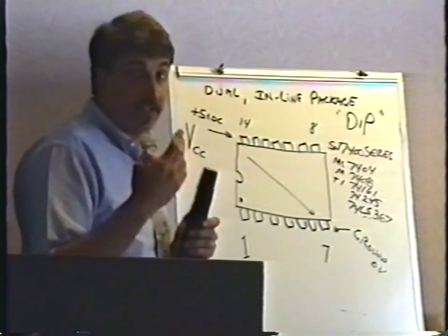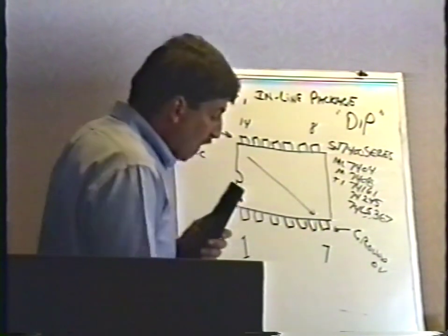And with the power turned on, I just go right across those chips. Now, when you do this, really important, it's very easy to slip with your meter lead. So, you want to be careful because the power is turned on now. When you put your meter probe on this thing, don't try to put your meter probe right here on the top of the pin because, bam, you can slip and short these two together. Put it here instead, in between the pin and the body of the chip, like that.